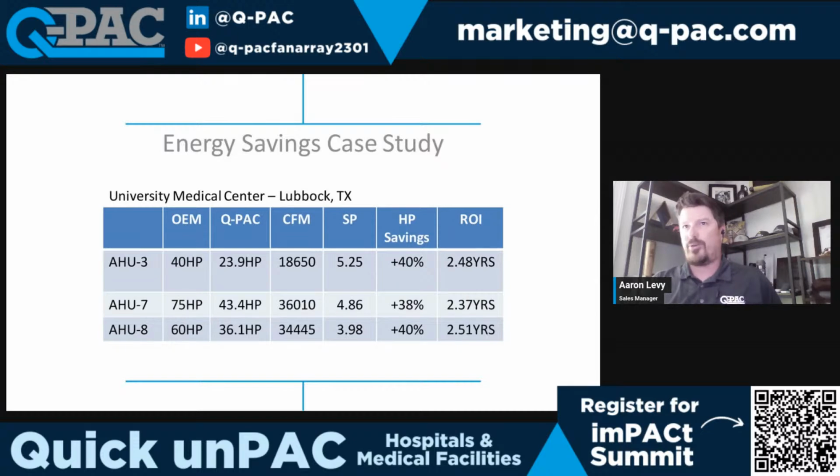So when you're talking double width, double inlet blower style solutions, you're somewhere in the total fan efficiency grade of about 15 to maybe 30%. Direct drive systems can improve on that, and they're somewhere between about 28 to 42%, somewhere in that ballpark range, depending on if you've got a really good wheel. You can probably bump that up a bit more, but it kind of stays in that range with the drive loss. And then you look at EC fans that can be somewhere between 35 to upwards of 70% total fan efficiency, depending on where it operates on the curve.